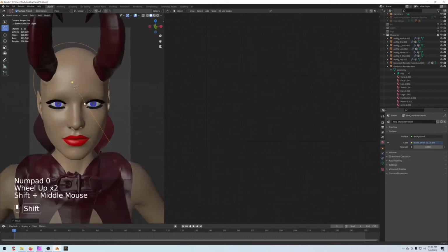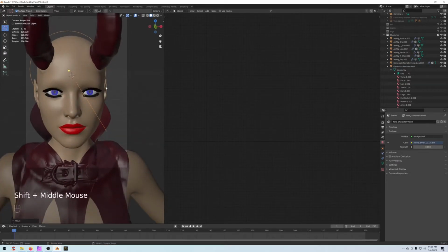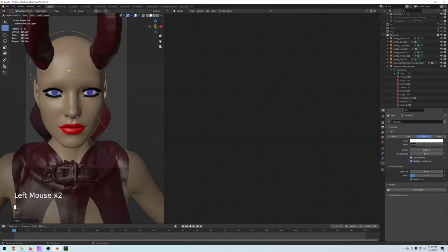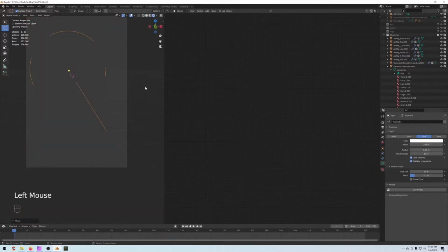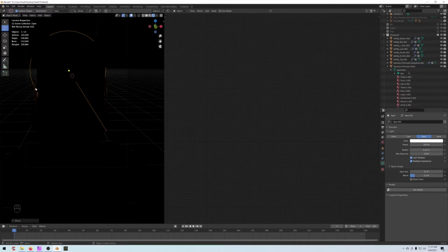All right, and what we should get is just like in real life. If you would do this in real life, you should see the ears glow a nice red. And so we'll turn up the watts on our spotlight and do a test. And when you get to white, it's too high. That means the red, green, and blue values are all exiting the mesh before they scatter. So this looks like it's a little high.